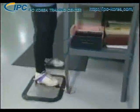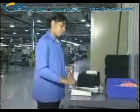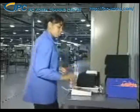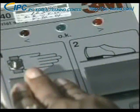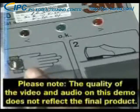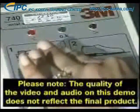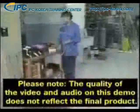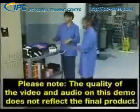When testing the wrist strap, remove both feet from the metal plate and use the opposite hand to press the test button. Shake your wrist to check for intermittent failures. If the test results in a fail high light, that means there is not a good ground connection, and we may cause ESD damage to the parts. If the test results in a fail low light, that means that the ground connection is too good and may result in electrical shock. If you experience any problem with personal grounding devices, let your supervisor know immediately.